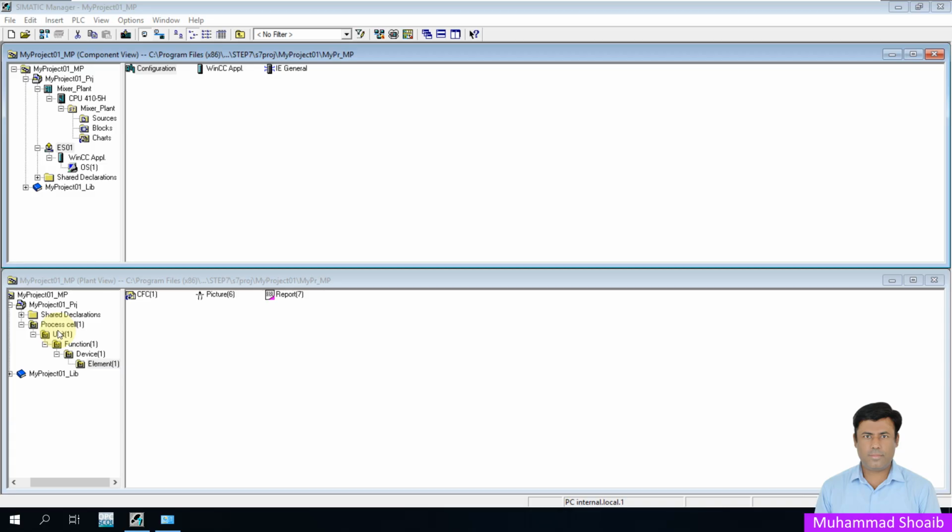The plant hierarchy typically consists of multiple levels, such as the plant, the top level representation of the entire facility, then the area, a subsection or department within a plant, like the processing or production area, packing area. Then units specify the equipment groups or processes within an area, like reactors, mixers, and then the device level, individual components like the pump, valve, or sensors.